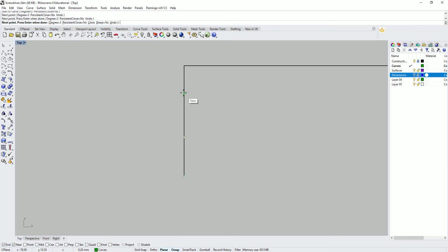So the next thing is, let's make the far end curve, and we'll make this a relatively tight radius here. So I'm going to choose this point here. I'm going to choose my corner point and another point right here. And you can see that that makes a fairly tight radius curve. The closer your control points are together, the tighter the curve of your radius will be.